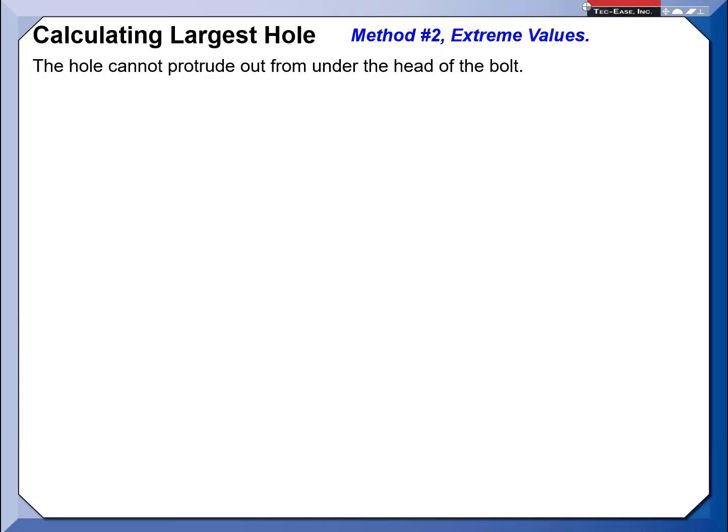I also took, based on drill sizes, and believe it or not, ASME has a standard on clearance hole size. I did a whole chart for them based on a loose fit, close fit, or what they call a normal fit. I did a whole cheat sheet for them. They could actually look and derive all these.